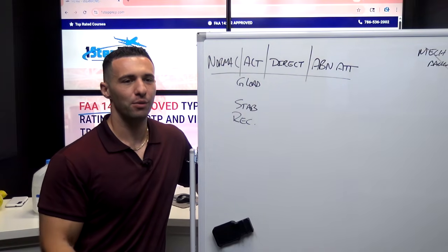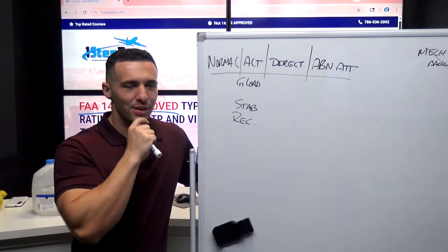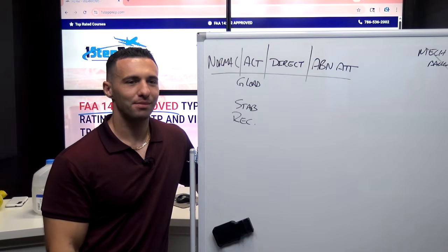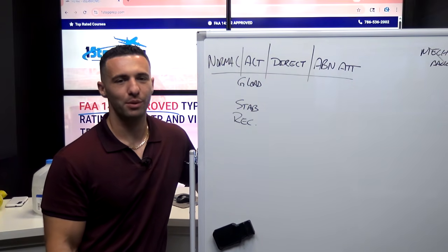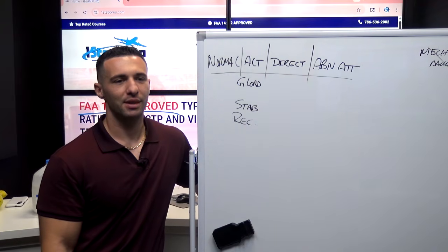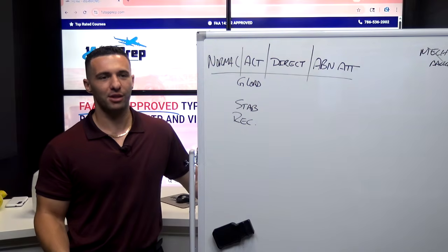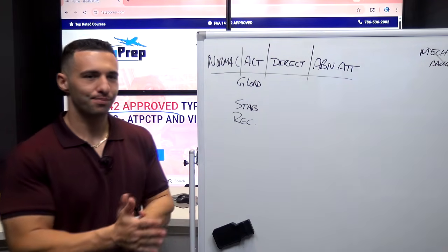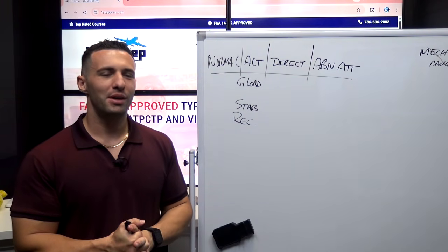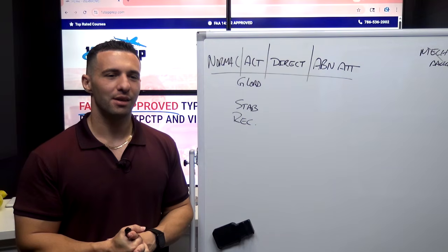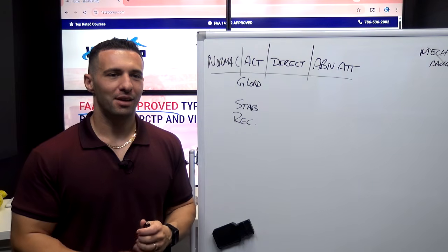What else we have here? How do you know you're in alternate law with or without the stabilities? There's no indication, Rick. It doesn't say you're with stabilities or without stabilities. I guess if you approach to where the stability would activate, you would know. But there's no direct indicator that I know of that says, hey, you do or do not actually have the stabilities. Neos behave a bit different in the flare mode. They do. The 321 Neo is kind of an interesting jet to land, in my opinion. Just my experience of it.